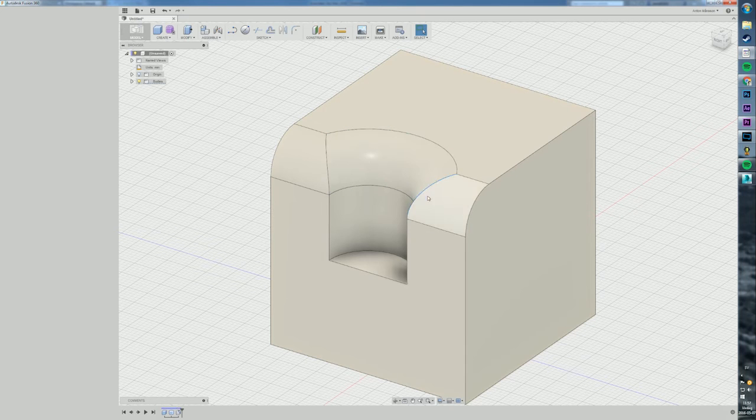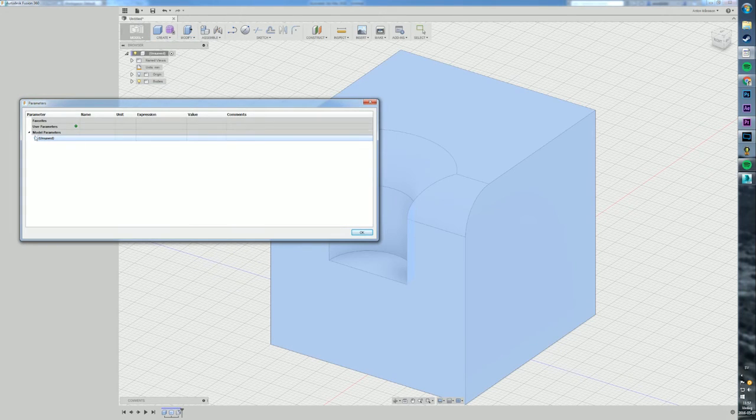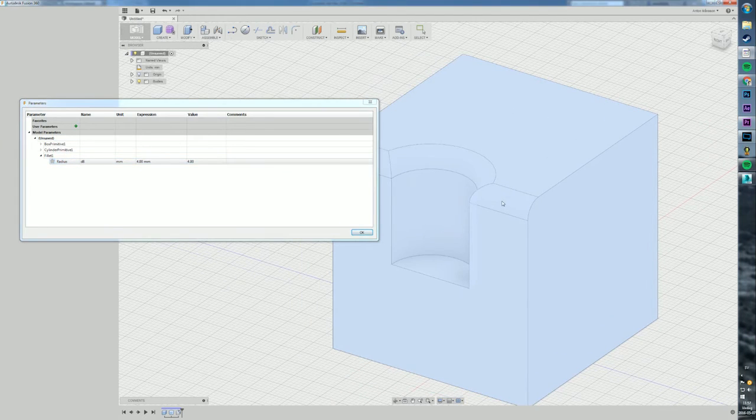With surface models, you can of course just go back and edit the parameters, which is really cool. So let's have the fillet here. I just want to change that to 4 millimeters instead. I can do that. So with solids and surface models, surface models are like a bridge between organic polygon modeling to more mechanical engineering. So what you can do with solids is, let's imagine that you're a designer, you're supposed to 3D print something. You want to have the ability to go in and change measurements like this.